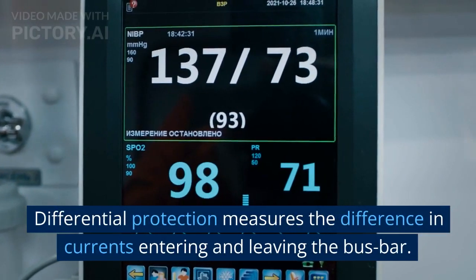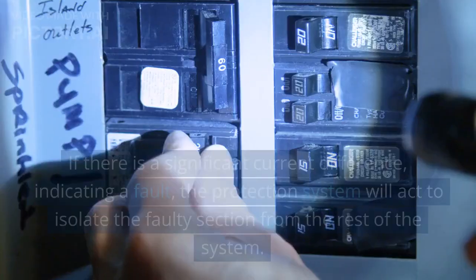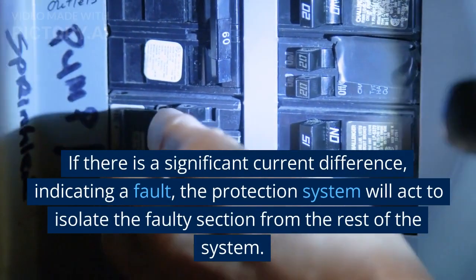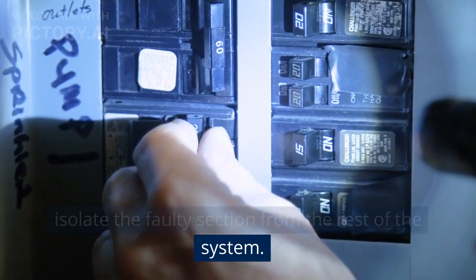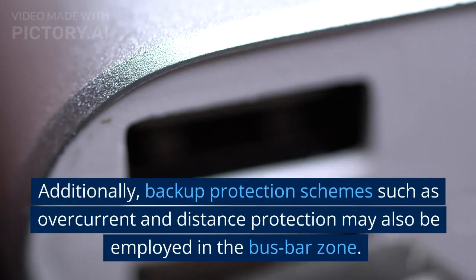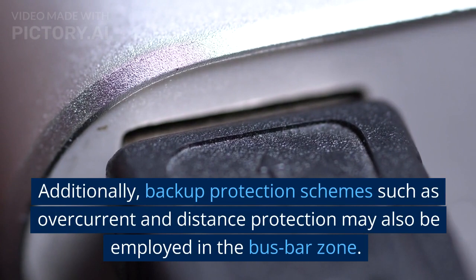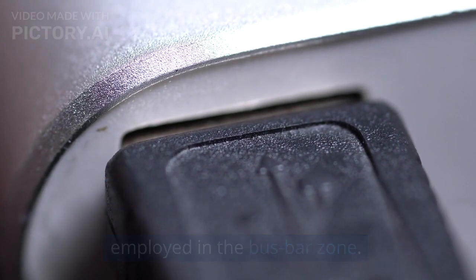Differential protection measures the difference in currents entering and leaving the busbar. If there is a significant current difference, indicating a fault, the protection system will act to isolate the faulty section from the rest of the system. Additionally, backup protection schemes such as overcurrent and distance protection may also be employed in the busbar zone.